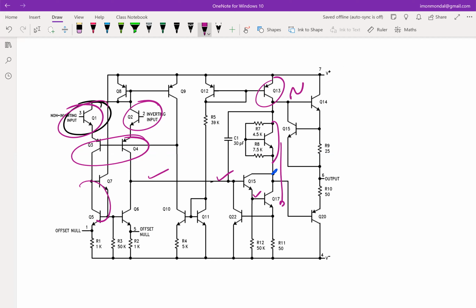So you have a voltage swing here, you have a voltage swing here, and this output structure you have done in one assignment in terms of MOSFETs. You had an NMOS on top, PMOS on bottom. This is what it is, because the output impedance looking in is of the order of 1/gm, right? So that essentially is your 741 op-amp. Everything else that you see is essentially done for biasing purposes.